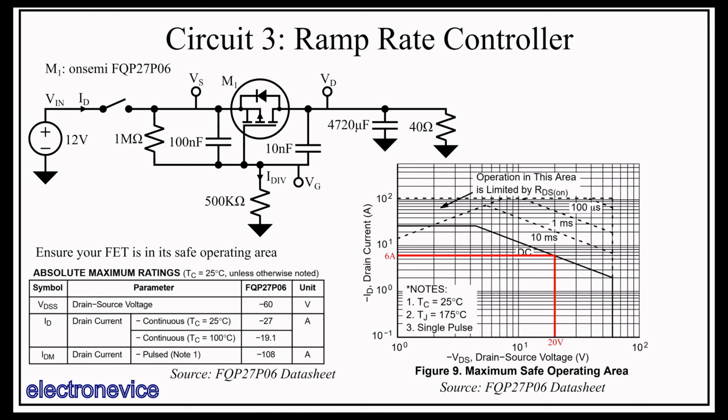Before we conclude with this circuit, there is one final very important thing we need to discuss that can cause a big headache if you do not keep it in mind when designing circuits like this: the necessity of this 100 nanofarad capacitor on the gate source junction. The gate source junction capacitance hasn't been discussed much thus far, apart from causing an error from our assumption that the Miller plateau is flat when in reality it is not.